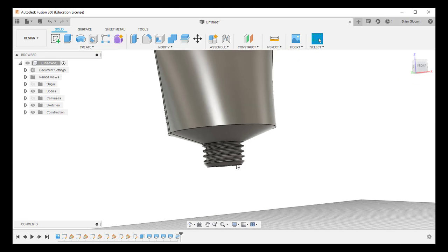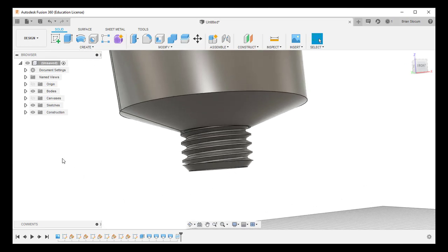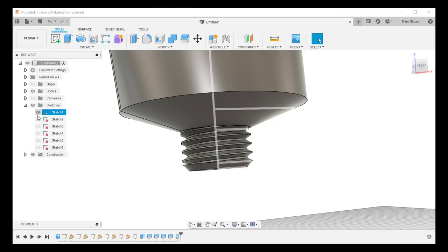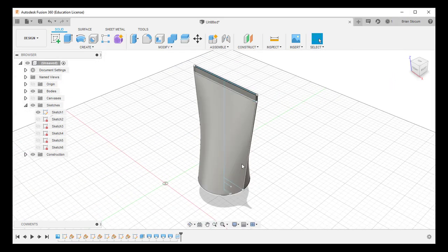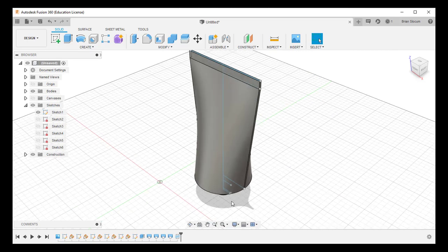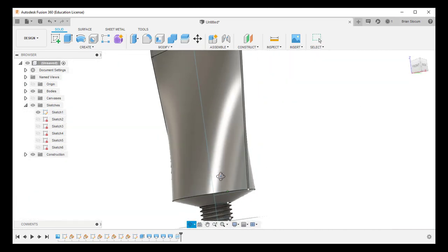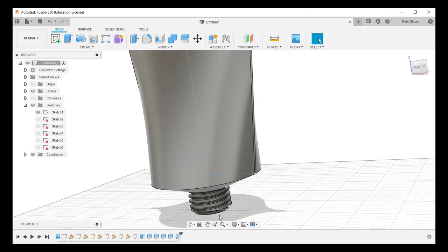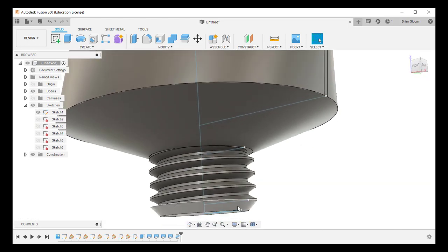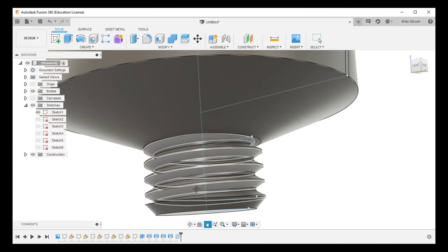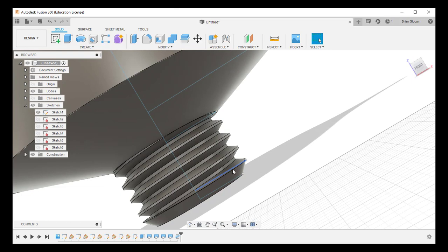And the other thing I want to show you is that that first skeleton or armature is there. And so if I go to sketches, that was my very first sketch. I can turn it on, and you can see that my armature exists. And because all of these points are referenced to my armature, I can make some adjustments in the moment to clean some things up if I start to get funny geometries here. So that point, these are all click and draggable, so I can squirt that in a little bit and it will start to change that interface.